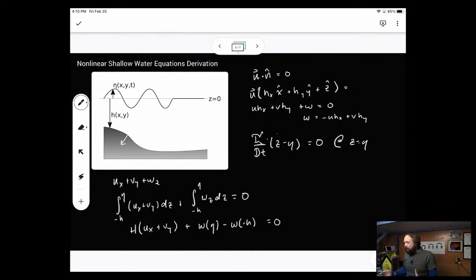It's kind of a weird statement, but what it ends up allowing us to write, so one, the material derivative of z, the material derivative of the vertical position, is just the vertical velocity. And I got minus d eta dt, the material derivative, is 0. And eta only depends on x, y, z, and t. So I can manipulate things a little bit here, basically move that d eta dt to the right-hand side. And I've got my boundary condition for the vertical velocity at the free surface.